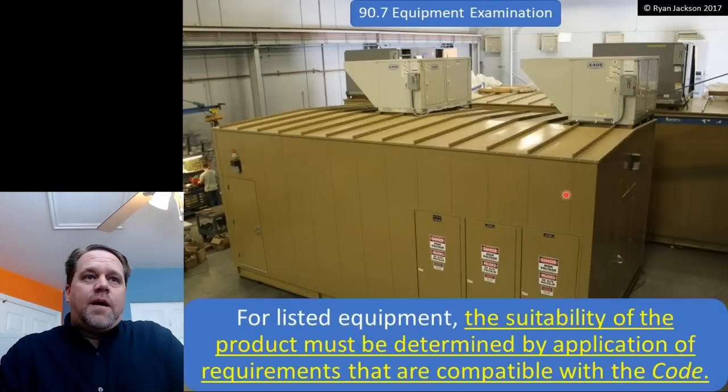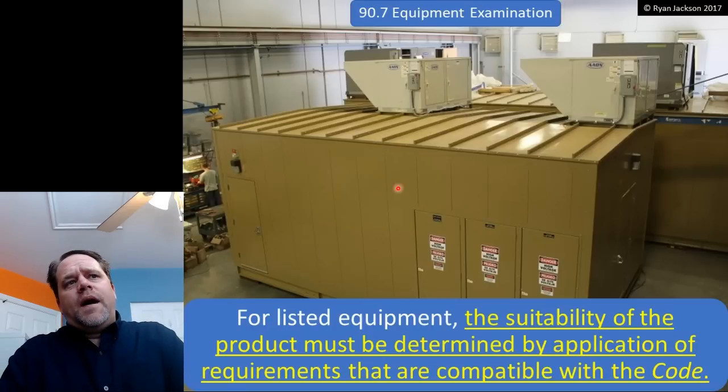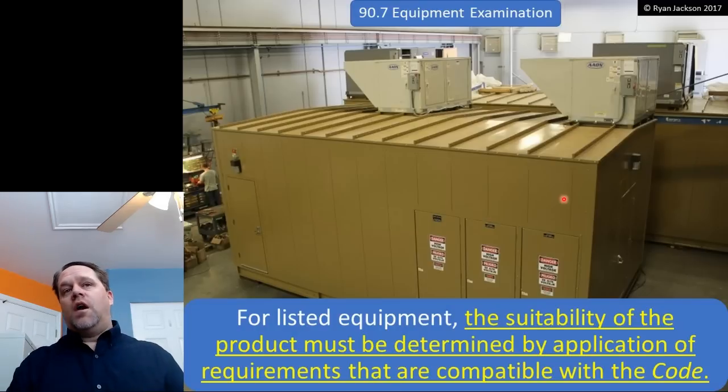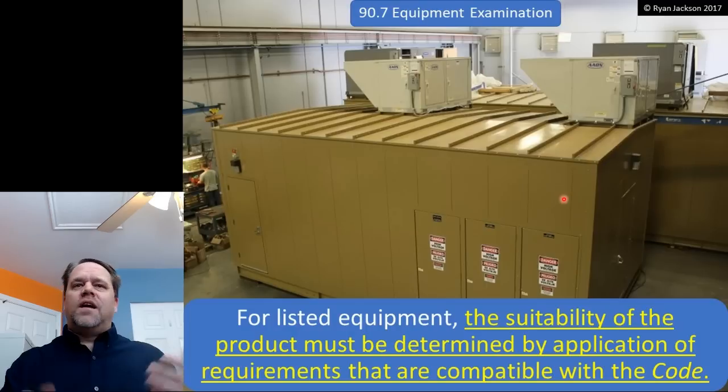But let's say that the panel inside of there is over 6 feet wide and it's 1200 amps or more. That might mean that I need 2 ways out of this building. I still have to provide 2 ways out. Whether it's listed or not, it still has to comply with the code. So that's what 90.7 is saying. It still has to comply.